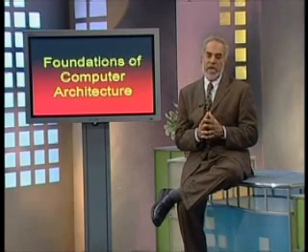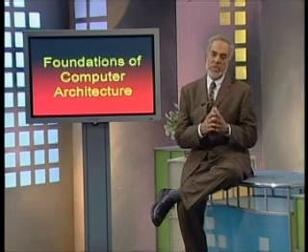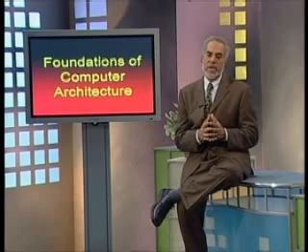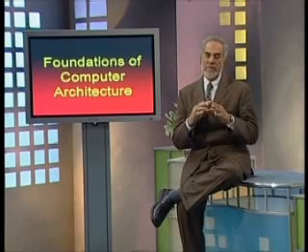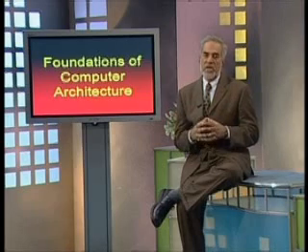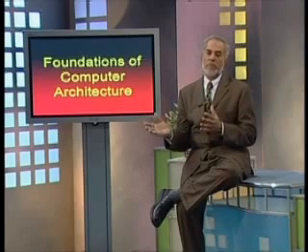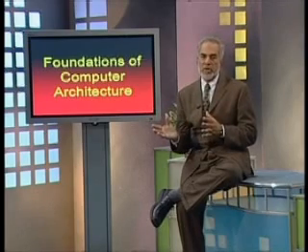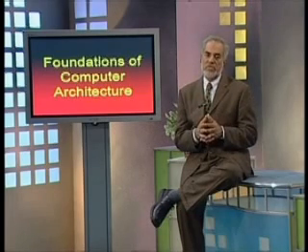We said we could have a CPU which is based on an accumulator. Accumulator based architecture means that we have just a register where we have one of the operands, the second operand comes, for example, from the memory, and the result is again placed in the accumulator. So a limited number of registers are there.